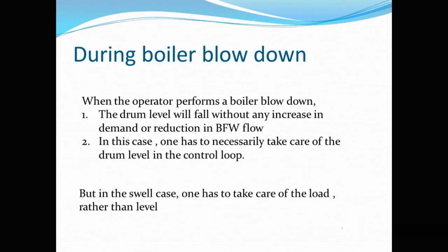So we cannot have a controller just to maintain the flow from the steam drum. We have to necessarily take care of the drum level also. So here also there are three variables: drum level, steam production, plus the boiler feed water flow. When they work together, the level can be maintained.